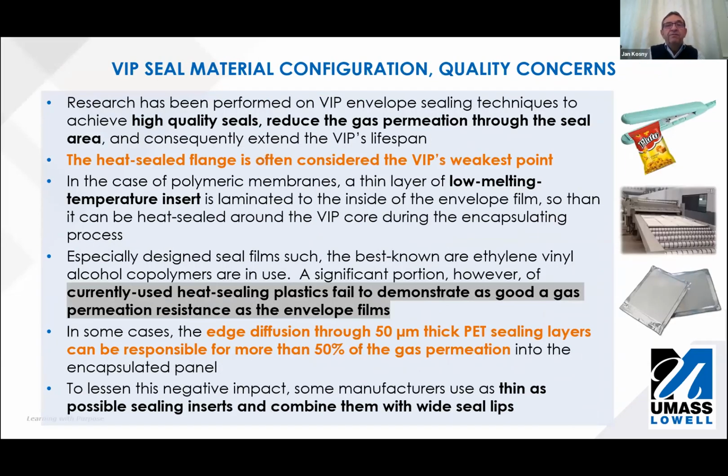Another important factor is that this membrane, which is covering the core material, has to be sealed somehow. And the design of the seal and the components of the seals are very important. It's good to remember that about 50% of the gas permeance into the panel is sometimes dedicated to the seal quality.